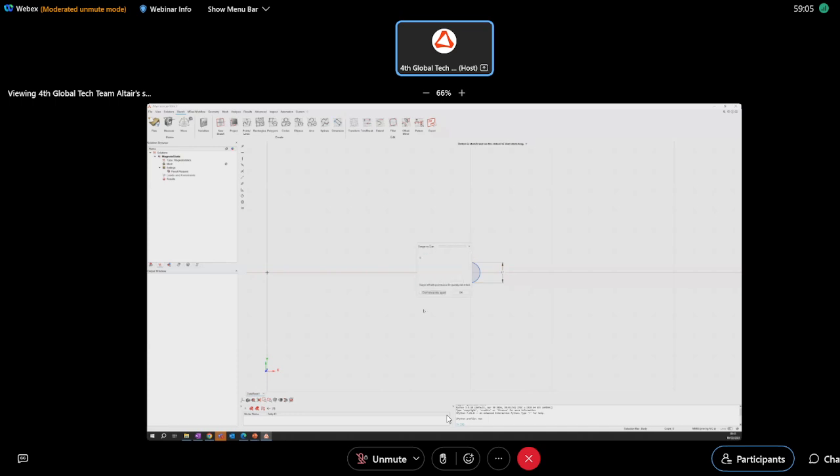Right click, or just ESC, to exit from the tool. You can avoid having this window later. Okay. So second thing, we want to dimension, for example, the position of the wire. So we can click again on the dimension tool, click on the center, and do the second click here. Okay, so you can see the dimension will appear. You can drag and drop and position it, clicking when you are confident. And you can enter 10 because we want to position the wire here. So enter.